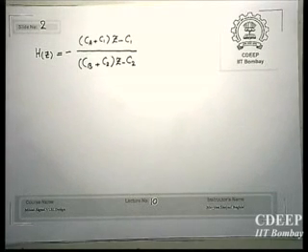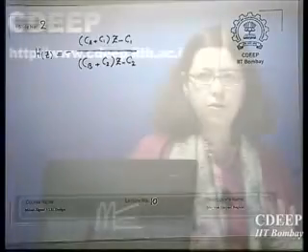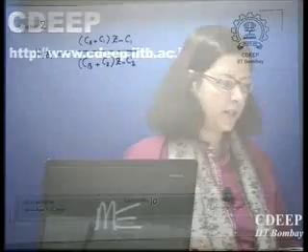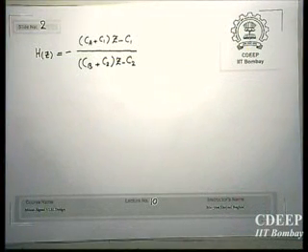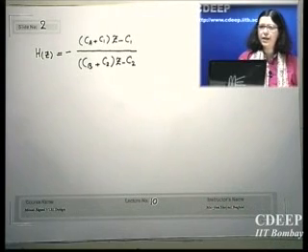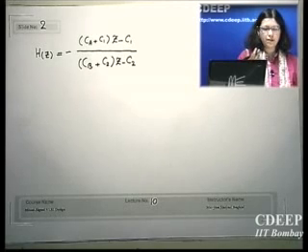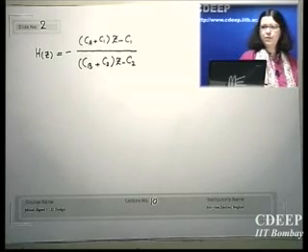Okay, so this is the transfer function of the first order switched capacitor filter considering C1 and C2 both present. Therefore, we will have one pole and one zero. However, if you notice, the corresponding filter in the continuous time domain doesn't have a finite zero, but here we will have a zero, which is at Z equal to minus 1, omega equal to pi. And omega equal to pi actually is the wrapped version of S equal to infinity.